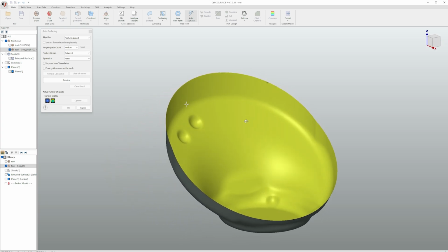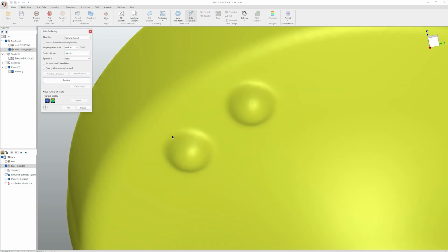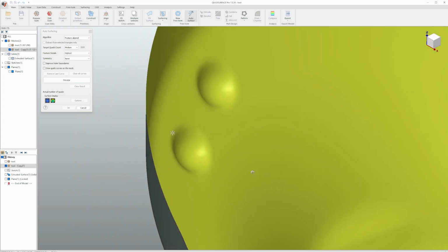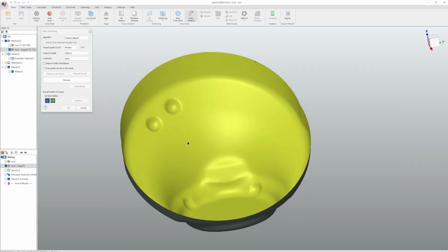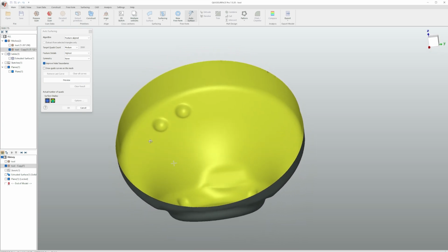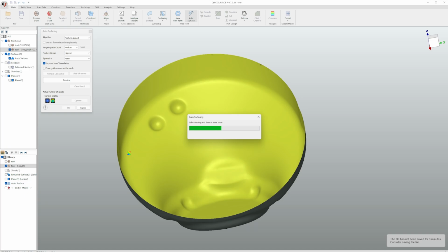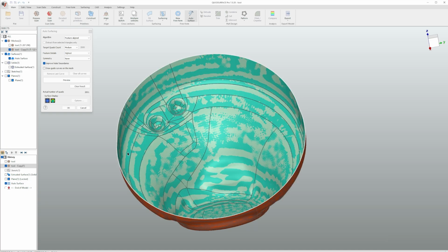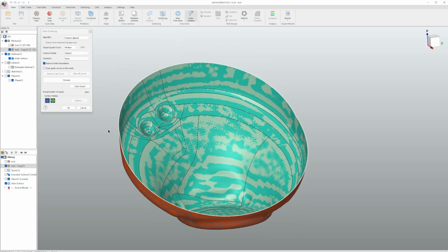To create this auto surface with the best accuracy, choose the highest feature details so that the software can nicely create these extrusions. Additionally, click Improve Holes Boundaries so it can become an even better fit. Then click Preview, and the software will do the job now. As you can see, the surface has been created, and we can click OK.